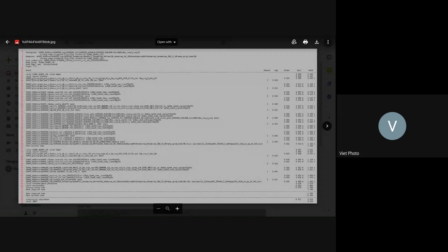So let's say this one goes to the A and Z, and then the net here. The arrival time here is 190 picoseconds. After the inverter, it becomes 205, so it increased by 16. That's the delay of the cell. Now it goes to the A here, the 7 picoseconds here.